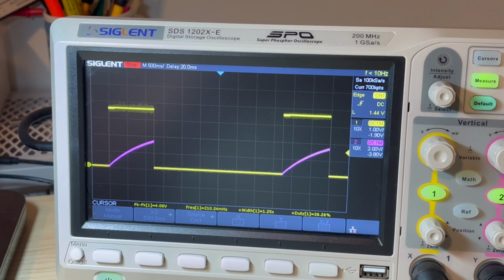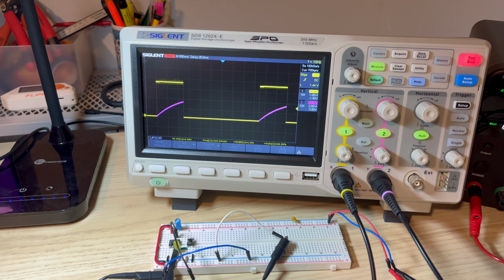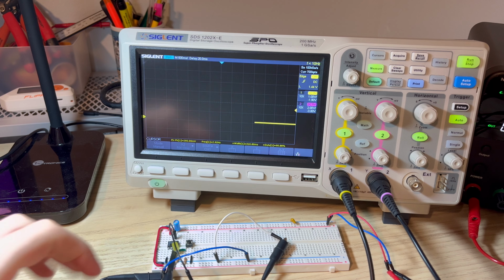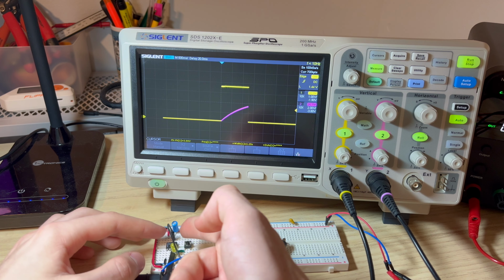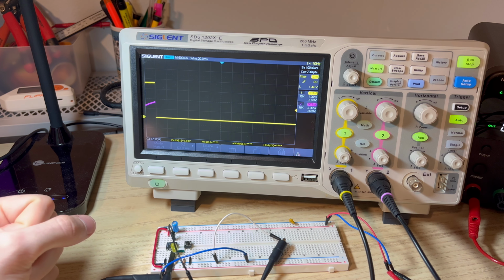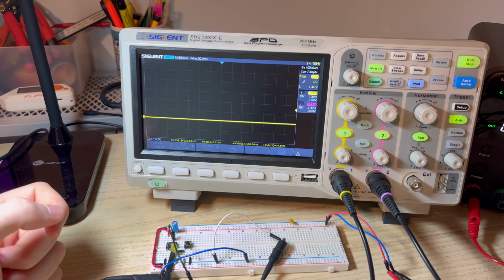You can see it deletes a lot of the noise. And this mostly helps with the astable circuit. You don't really need this very much for this circuit, but no, that helps a lot. Generally, you want to be placing this decoupling capacitor as close to the 555 timer as possible, but it's just a breadboard here, so not all about efficiency. You only really need to do that if you were making a PCB or something.